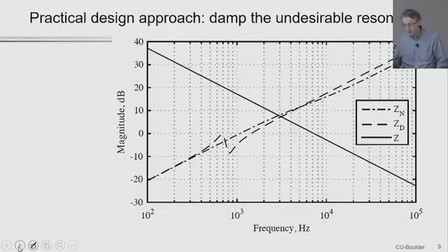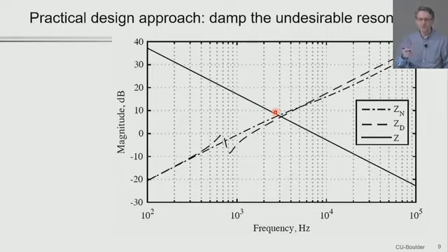All right, so going back to these undesirable resonances that we have right here, now we can think about ways to mitigate this problem. So let's see whether we can make the impedance Z, in this case here, so small it doesn't interact with Zn or Zd. In this case here, since Z is open, we would want to make it as large as possible, really, to avoid interaction.